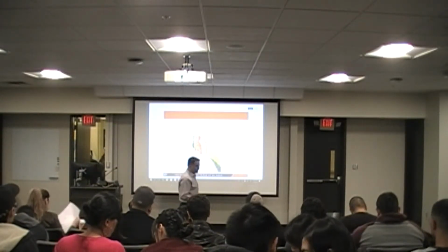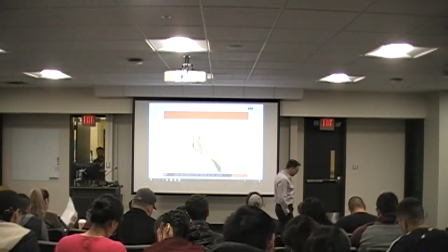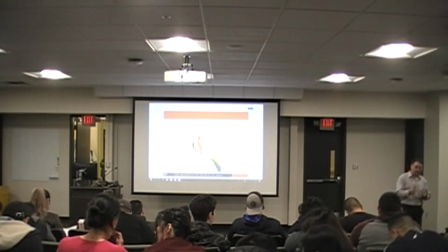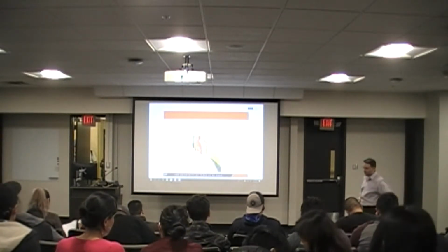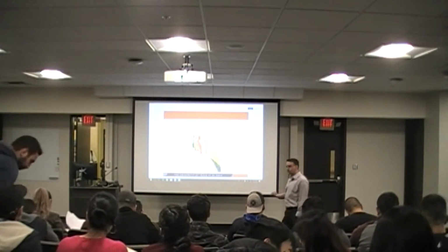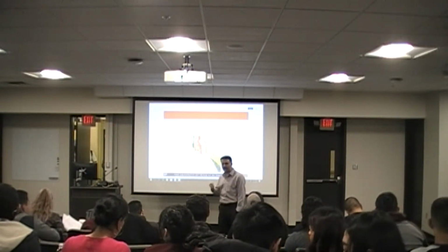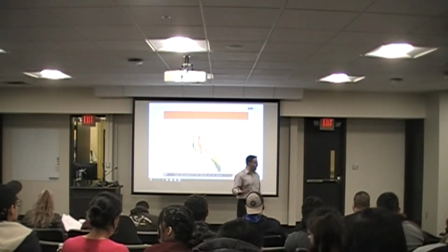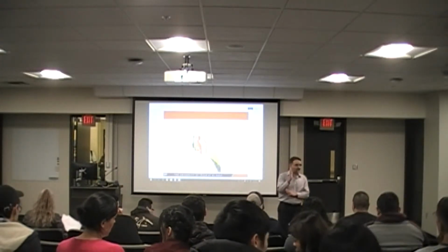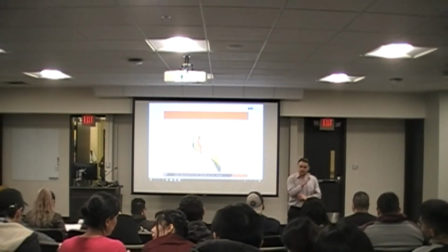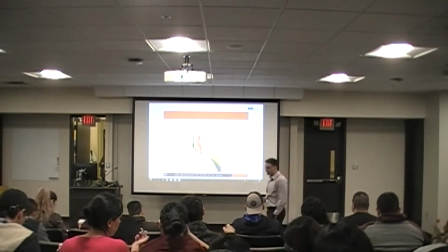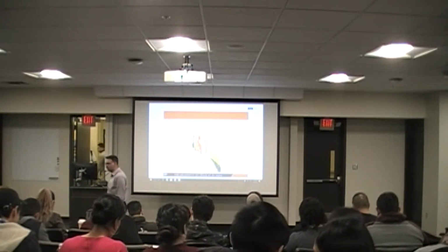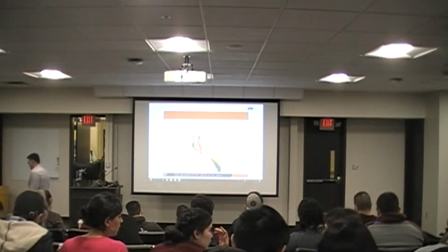We had an example, if you recall, when we talked about the issues with retaining structure. Right? When you have a backfill right behind the retaining structure, if you use material that are prone to shrinking and swelling, you basically will see the separation of the soil from the wall. And that basically defeats the whole purpose of having the wall. Right? The wall essentially is built for restricting the movement of the soil into the highway, for instance. So if the soil can sustain its own weight, there is, in fact, no reason for having that retaining structure.